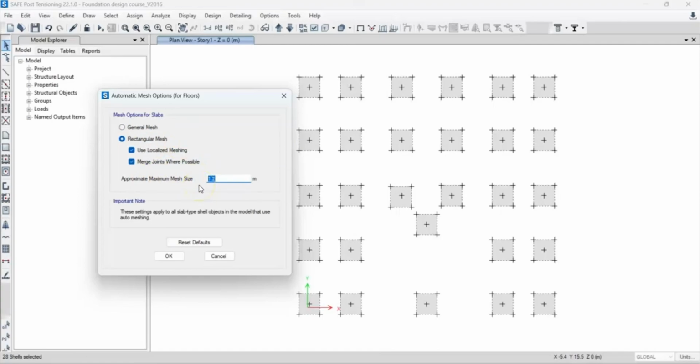So now this is where we need to input the size of the mesh. The size of our mesh is going to be 0.5 meters. Why are we inputting 0.5 meter? For a normal standard residential isolated footing, the footing area ranges from 1.2 meter to 1.8 meter in footprint and width. So a 0.5 mesh size is a structural engineering sweet spot, because it breaks a 1.5 meter footing into a clean 3x3 grid of sub elements, which is going to provide superb analysis precision. So that is why we are going with 0.5 meter.